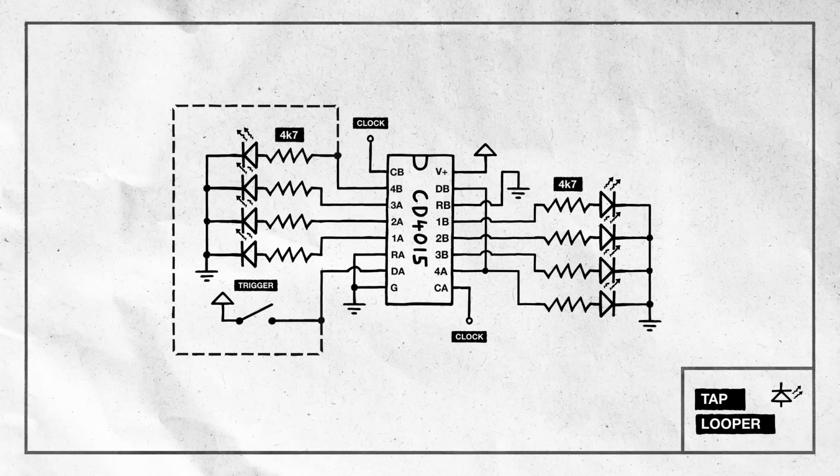Unfortunately, we can't just connect the last output to the data input like this. That's because both the output and the button are able to sink current, meaning that if either is high while the other is low, we create a short circuit. To avoid this, we'll set up 2 diodes. These will block any current from flowing in the wrong direction.